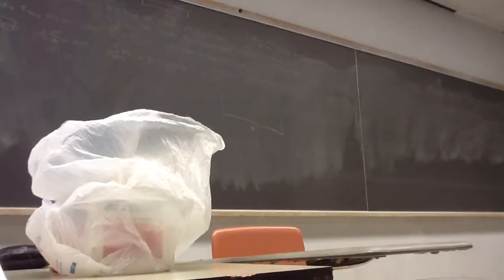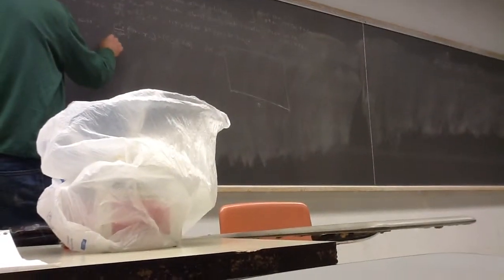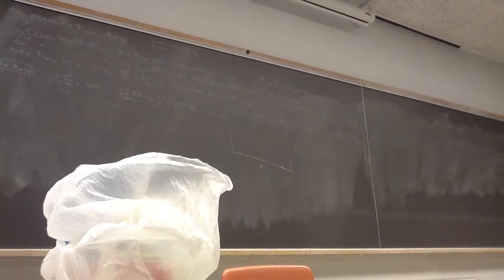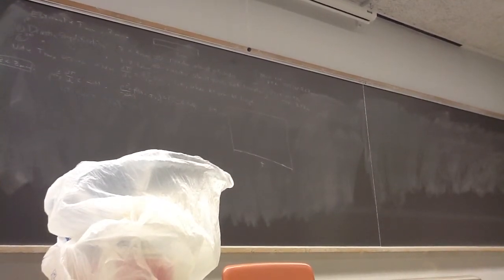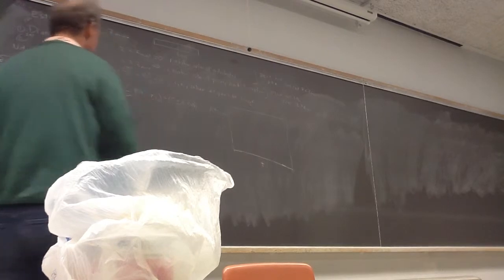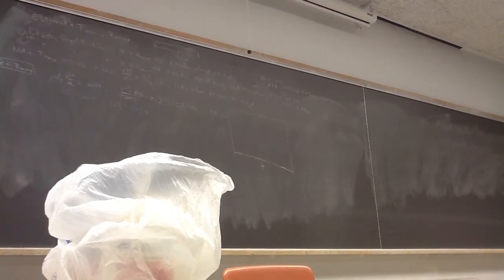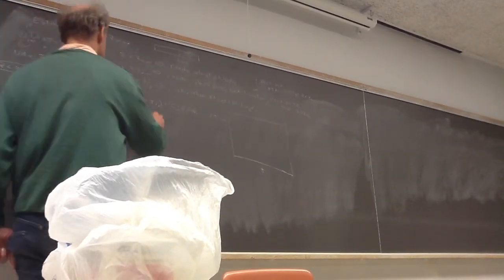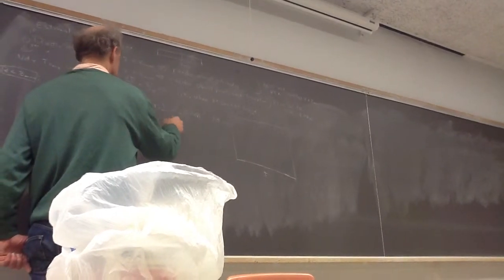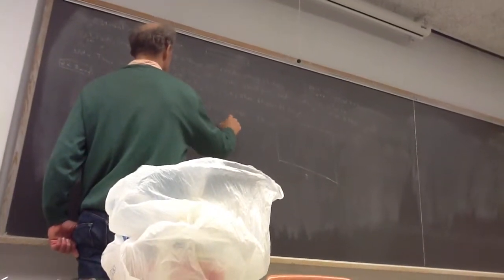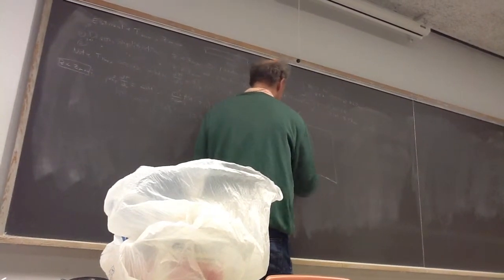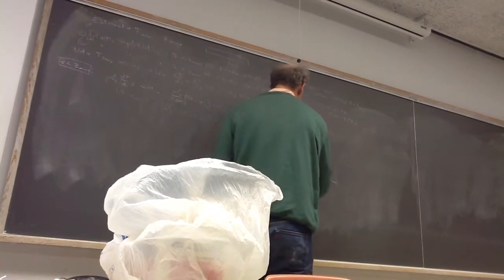Heat generation is minus RA times minus delta H. Can you see the blue chalk? Okay, so I'll find another color that you can't see. RA is going to be K, some sort of rate constant, times some function of C, times minus delta H. Okay, and let's try to plot what this looks like.